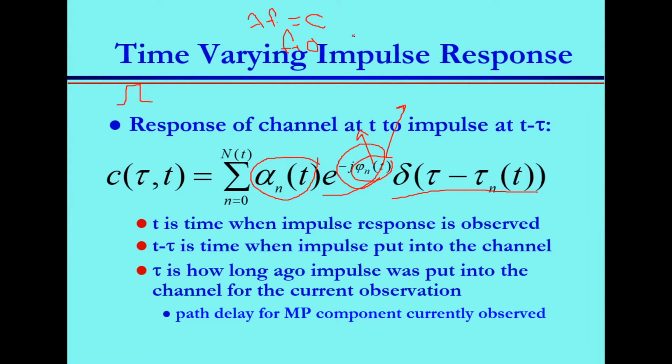So here, in this case, you just replace c to measure the Doppler shift. You replace c with the speed of the car, and f with the Doppler shift. And lambda is the same lambda because you are transmitting the same signal. Then you are able to calculate. And this depends on the angle. For example, if the movement of the car is perpendicular to the observation point, then the Doppler is always 0, because it depends on cosine